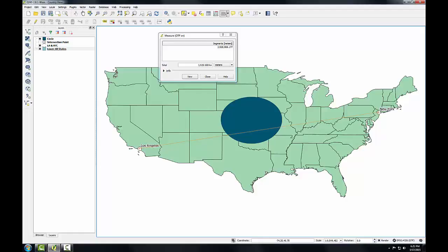So remember, for this projection in QGIS, coordinates are treated as spherical latitude and longitude. Distance is calculated as if along a great circle arc, and so the actual ground distance is preserved. Shape and area properties, however, are distorted.